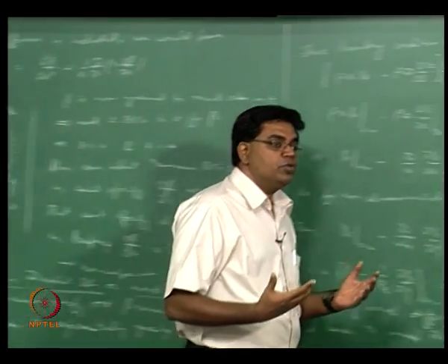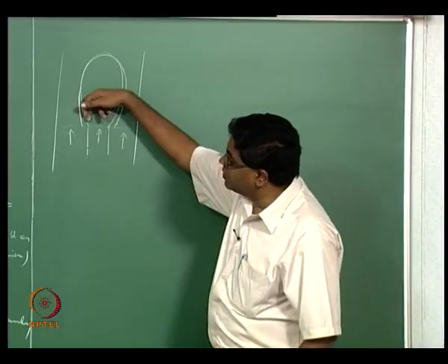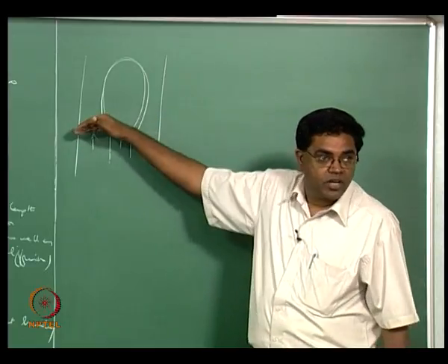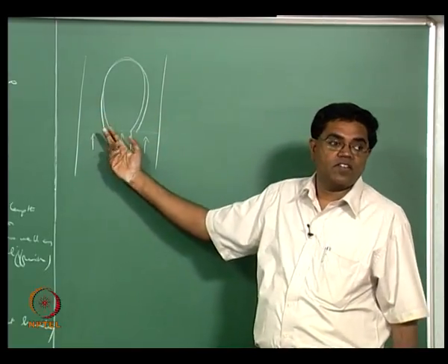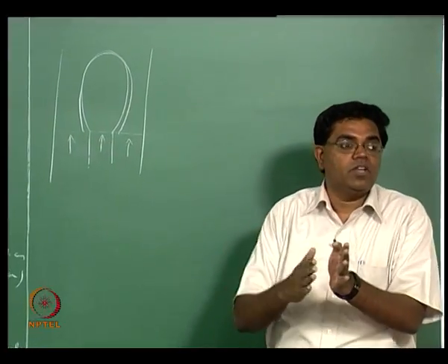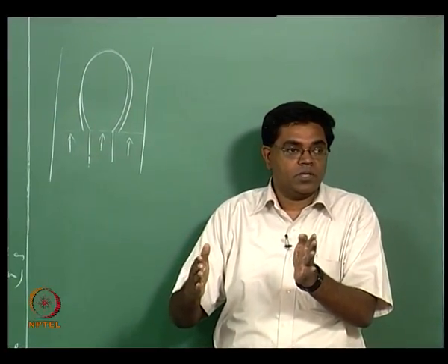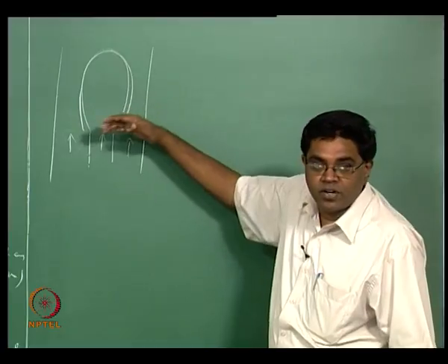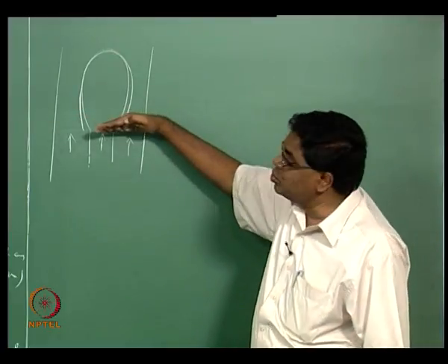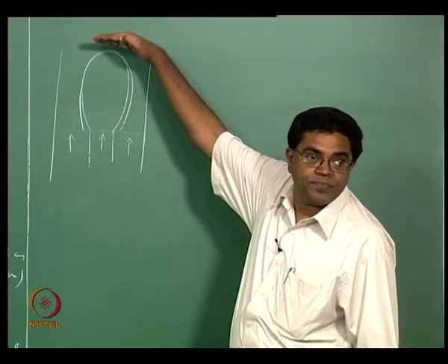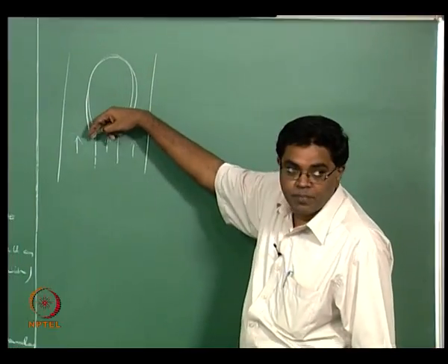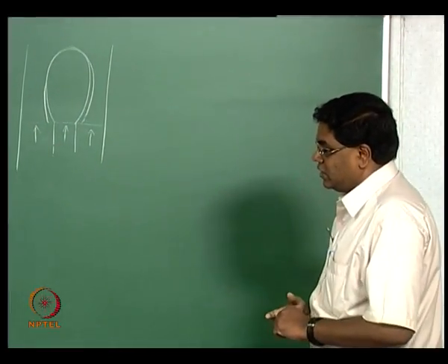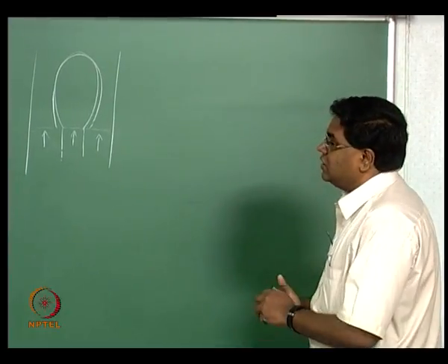But when you have axial diffusion taken into account, you can now permit mixing to happen this way across, upstream of the inlet to the domain, and therefore you could find the fuel and oxidizer being in stoichiometric proportions away from the lip of the burner. That's possible, and we are not strictly speaking drawing what's happening inside, because we are not solving for it. Our boundary condition is still applied only here, and our solution starts only into this domain, right? So we don't know exactly what's happening, but this is permitted. Okay, so this is the consequence of having flux boundary conditions along with axial diffusion taken into account